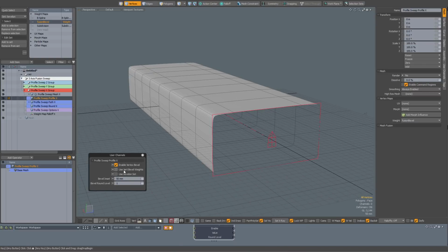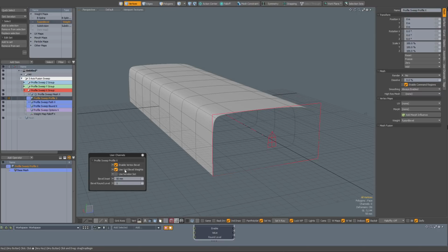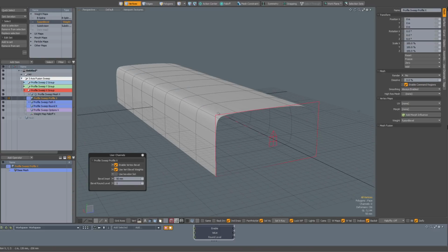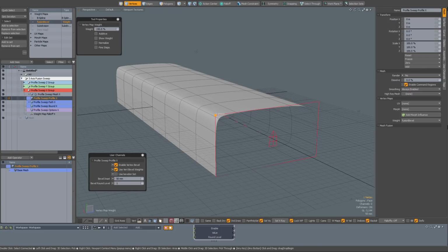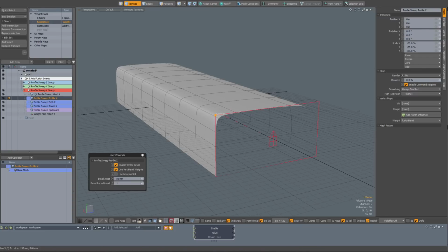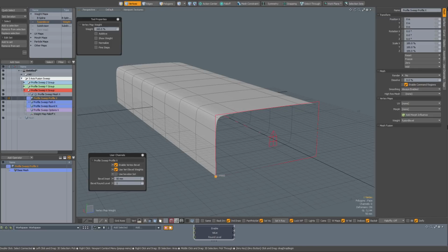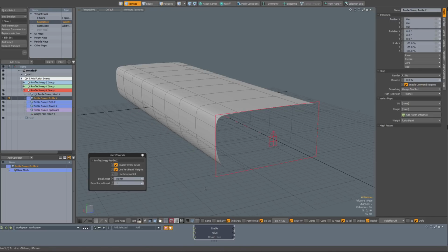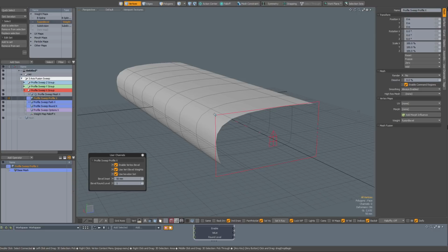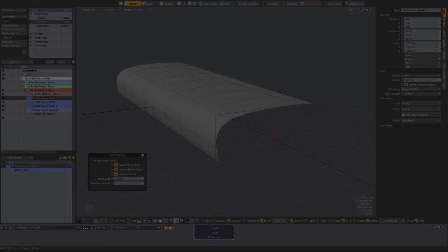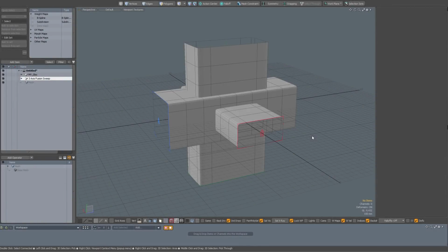When I turn it off, I can also say no, I don't want the regular bevel, I want to use the bevel weights, and with use bevel on set unchecked, all the vertices will get beveled, modulated through the weight map. So make sure that you have your weight map selected when you adjust the weights. Just like that. And you can also use the bevel on set, so vertices that do not belong to the set do not get beveled. So with that long and boring introduction out of the way, let's do some actual editing.